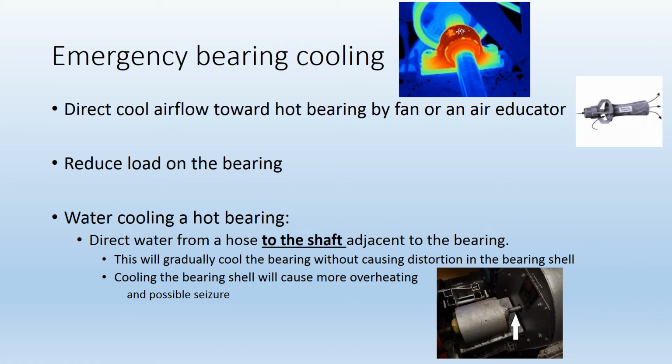That would be a very bad scenario, and this is the reason why. If you end up cooling the housing, the housing will start to shrink, and that shrinking of the housing will cause tighter bearing clearances, and tighter bearing clearances make more heat or even cause seizures. So you want to be cooling the shaft adjacent to the bearing.